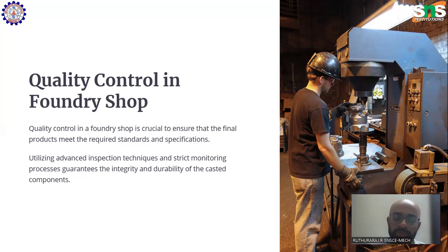One defect we already discussed is blowholes. Blowholes are caused because of gas trapped inside the casting. They can be eliminated by providing vents. Another casting defect is misruns. Misruns happen because of improper removal of the pattern. If the pattern is not removed properly, some edges may be deformed. Those deformed edges may lead to misrun.